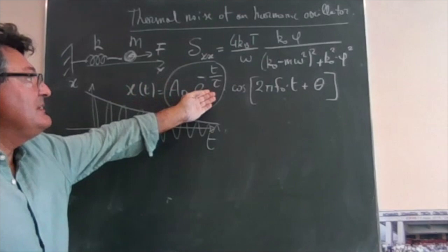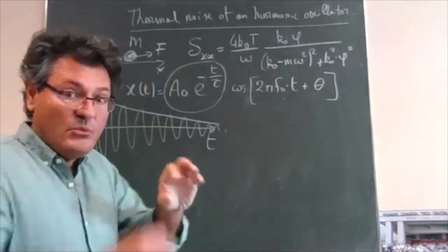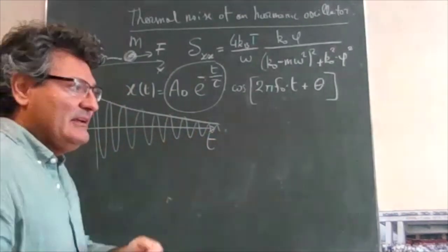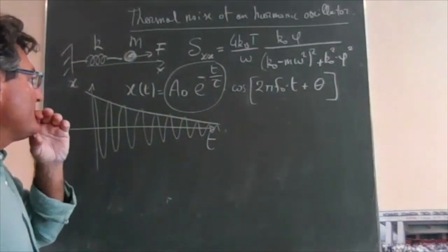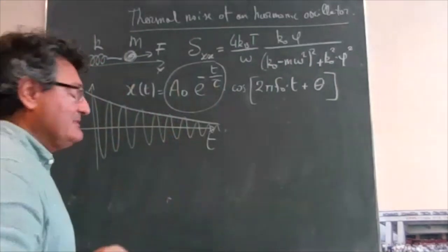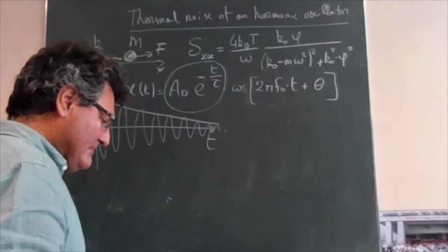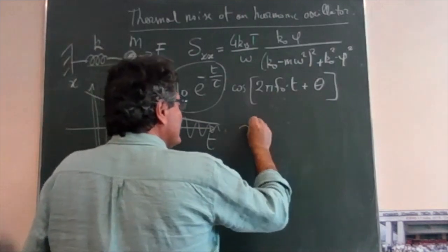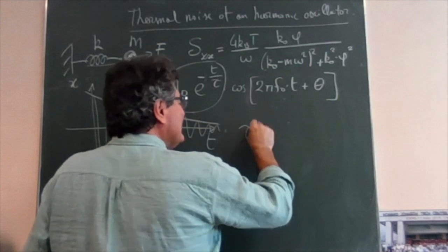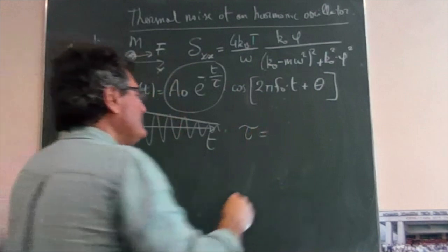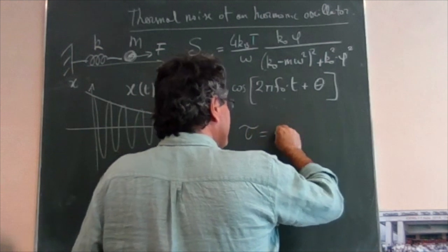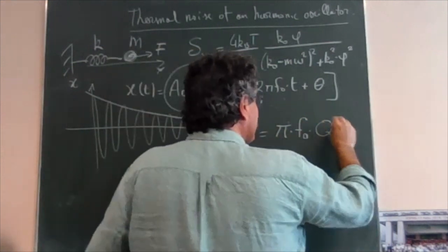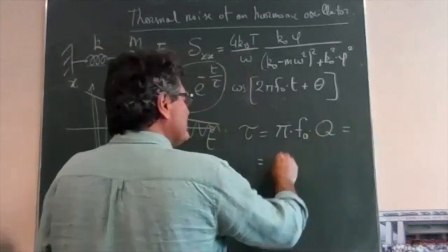Well, if we consider a harmonic oscillator, really simple, made by one type of material, and there are no other forces apart from the elastic forces inside the material, then the material is characterized by the loss angle phi that is related to the Young modulus.